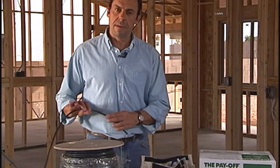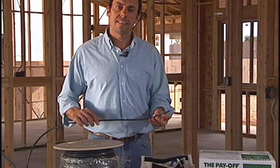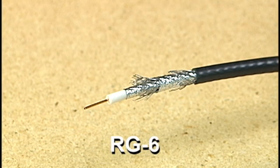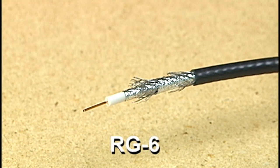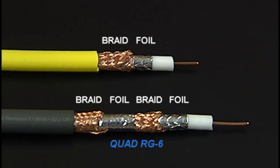The most common coax cable for residential use as recommended by the TIA standard is Series 6. The designation for Series 6 cable is RG6. RG6 has a very low signal loss. It's typically used for all broadband RF application infrastructure wiring in the home, such as cable television. It comes with 2, 3, or 4 shields, like this: an inner foil, a braid, foil, and braid.